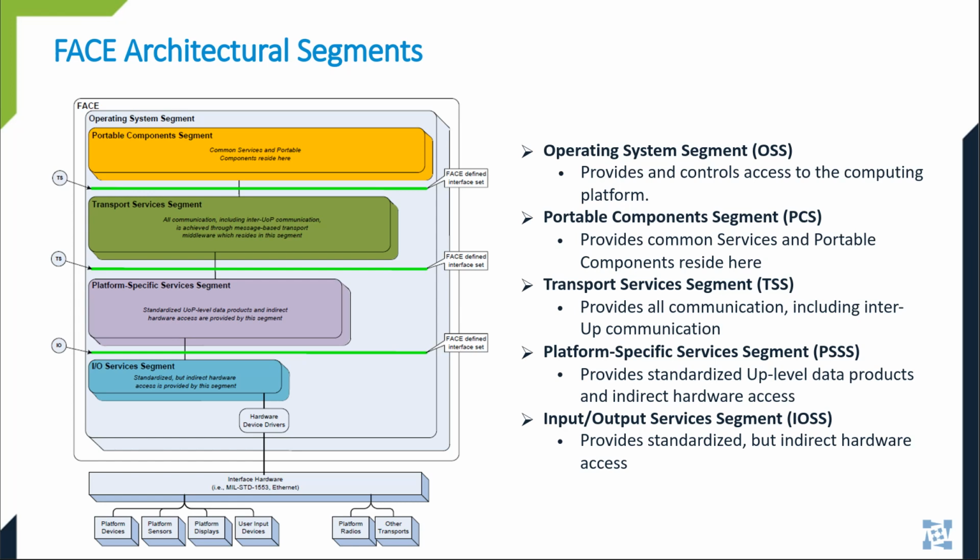They provide services such as management of data and translation, logging services, streaming media, health monitoring, graphics processing, and much more. An example of a UOP is Honeywell's device driver to convert raw 1553 data messages into a FACE data model. Then the input-output services segment provides the abstraction of the interface hardware and drivers from the platform-specific services segment. Anyways, these are the FACE segments in a nutshell. Wish we had a lot more time, but we don't.